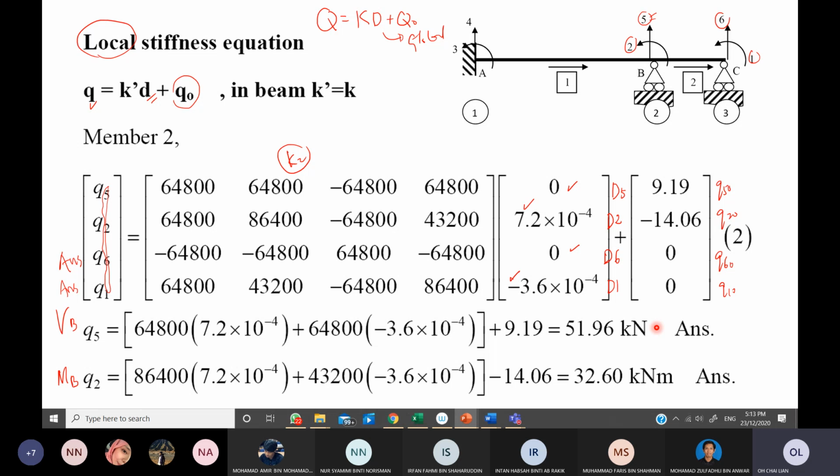But if you notice, you are obtaining the information at the nodes only, where you place the DOF. The one that you don't put, you cannot find it. So either you put a node there to find the answer, or you use the analysis that you have learned in chapter 1 to solve it, because it is already determinate. Many of these you already solved.